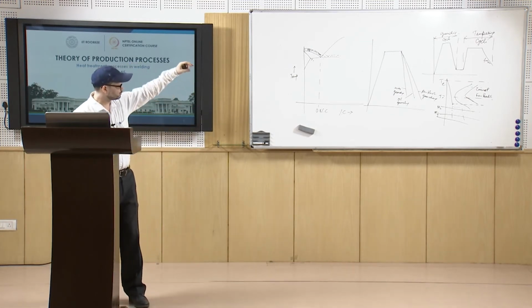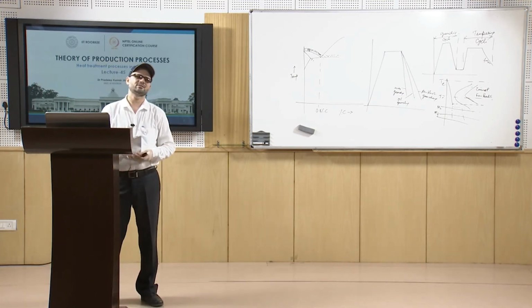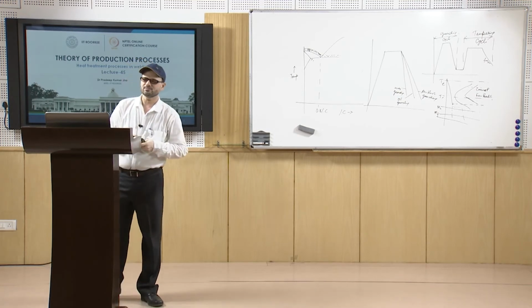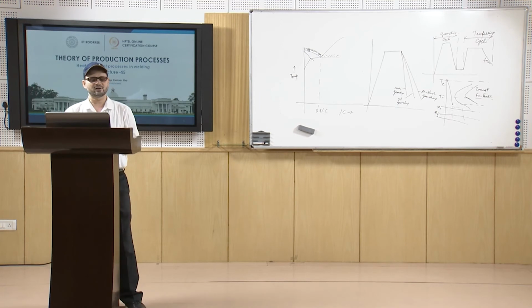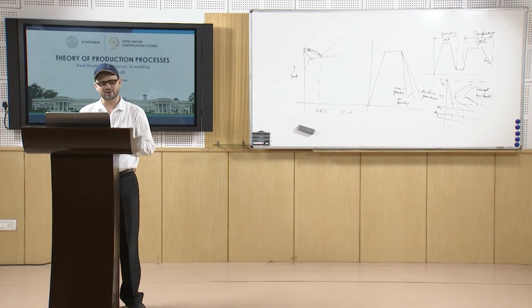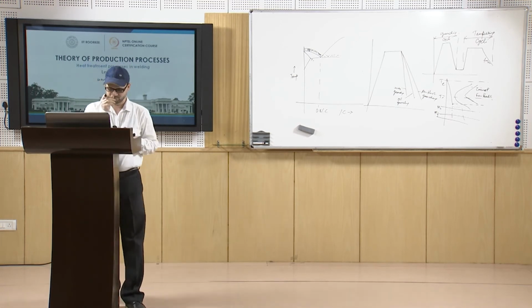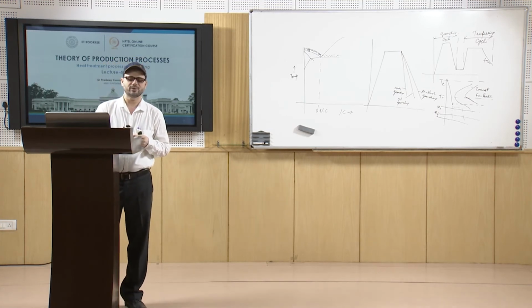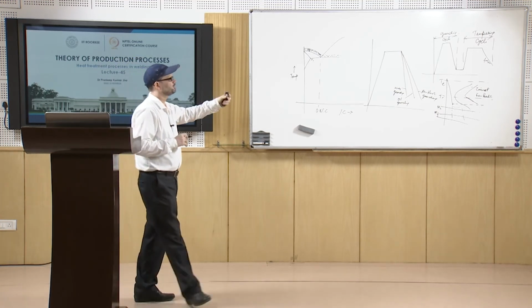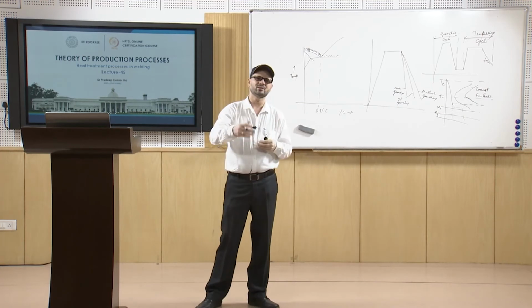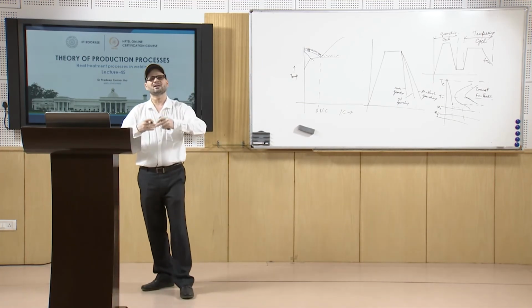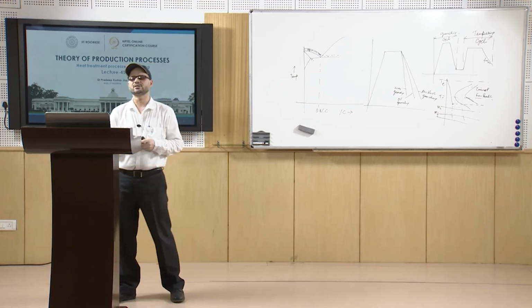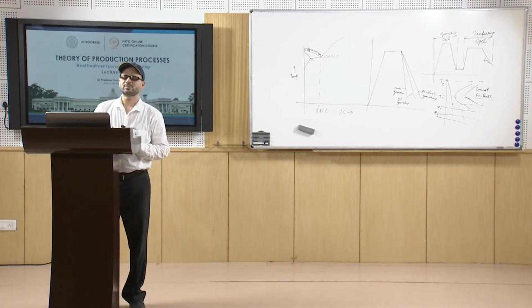The martensite you could have got earlier would have high brittleness, but in this case you do not get that much brittleness. This is also a special heat treatment process, given to get a good combination of mechanical properties for the welded specimen.